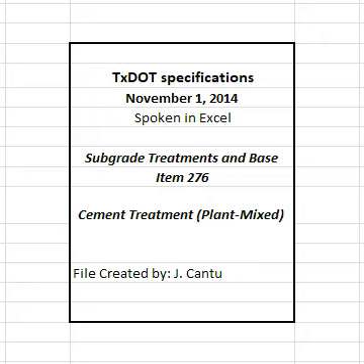6.1.1 Units for payment adjustment. 6.1.1.1 Roadways and shoulders. Units for applying a payment adjustment for thickness to roadways and shoulders are defined as 1,000 feet of treated base in each placement width. The last unit in each placement width will be 1,000 feet plus the fractional part of 1,000 feet remaining. Placement width is the width between longitudinal construction joints. For widening, the placement width is the average width placed of the widened section that is deficient in thickness.